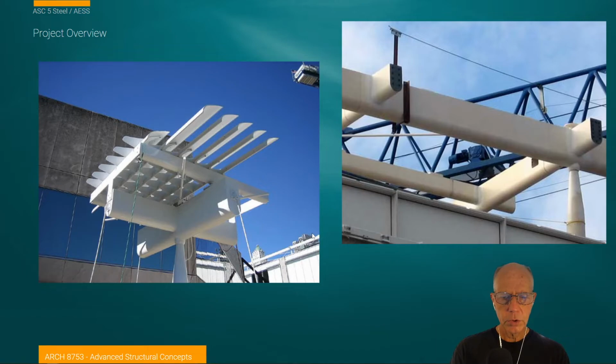And I've already shown you these two. What I wanted to do now is take a few minutes to show you some of the construction details of this project. This is where I got some of the data I was using and how I'm creating elements. Here on the left we have almost a full component assembly. We have the top of the column system. It comes to a point here. It looks like it might be a rigid connection, not a pinned connection, but because it's tapering, I think it's a mix between the two.